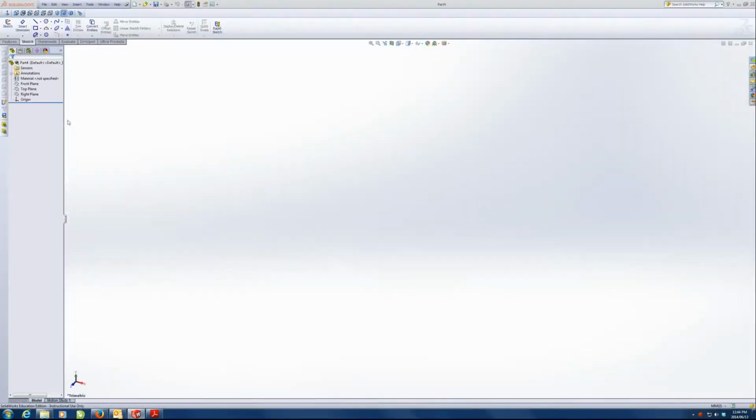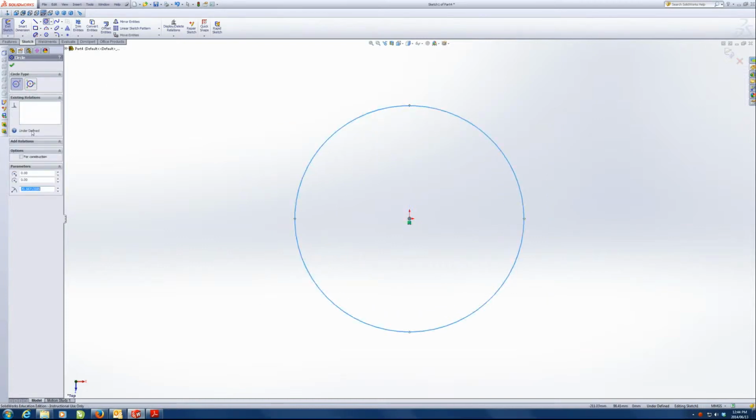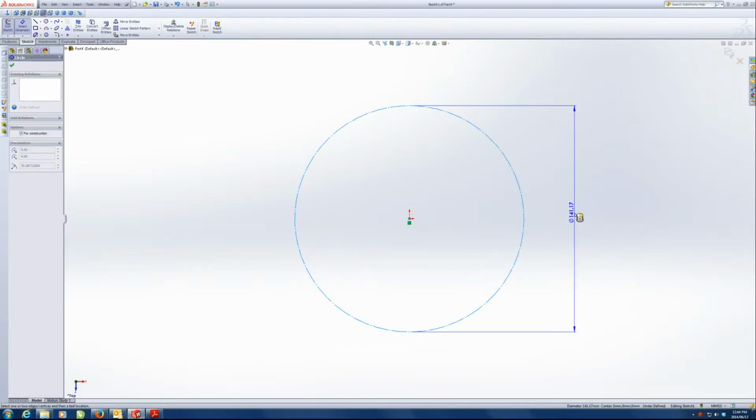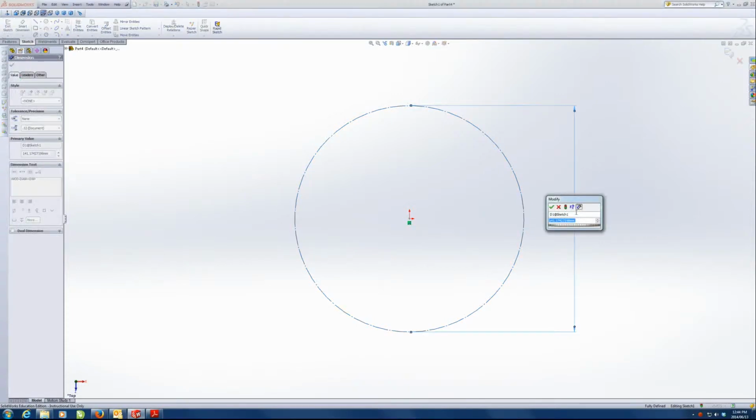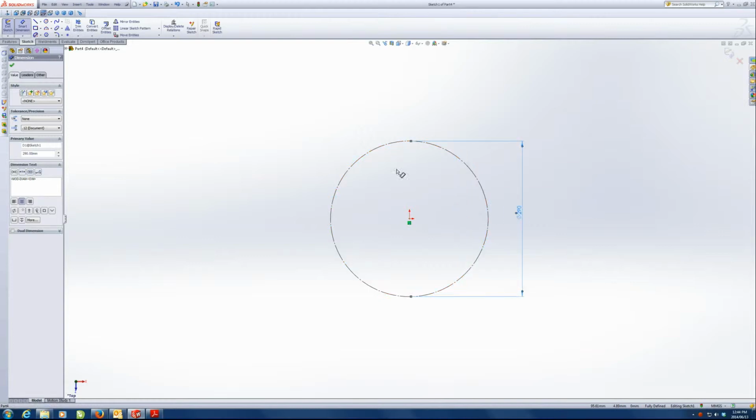I think the easiest way to start this drawing is to start with a PCD. We're going to draw the circle, but we're making it for construction. I know this seems sort of counterintuitive, but you're going to see now why we've done it this way. We know that this is 145 times 2, so 290, that's quite big. We can see that from the drawing, because we know the distance from here to one of the circles is 145. So now we're going to draw our 4 circles.